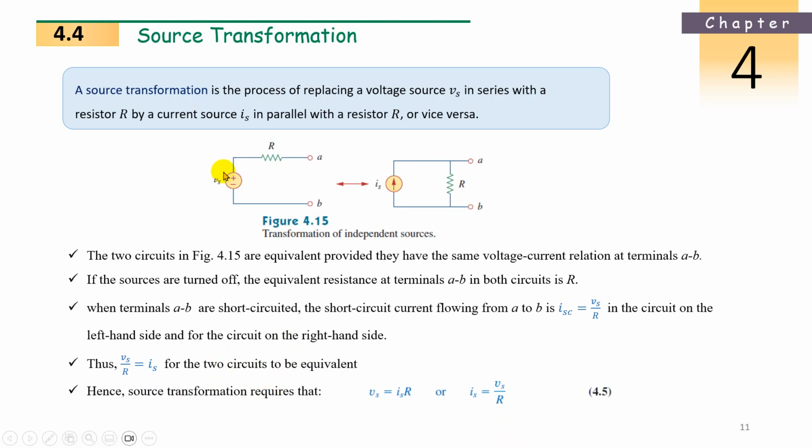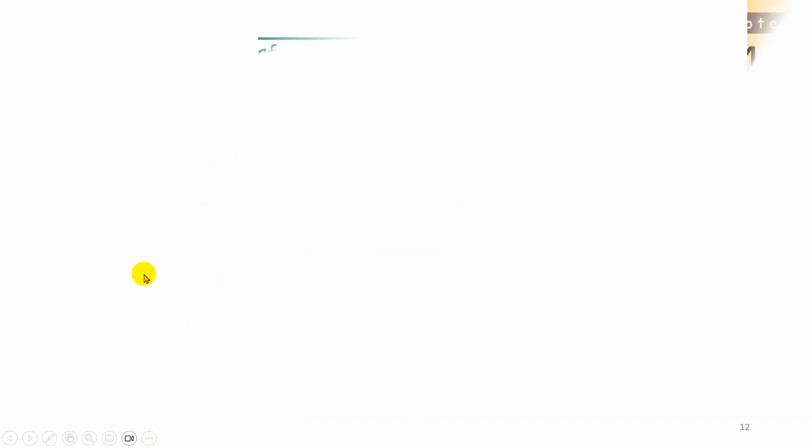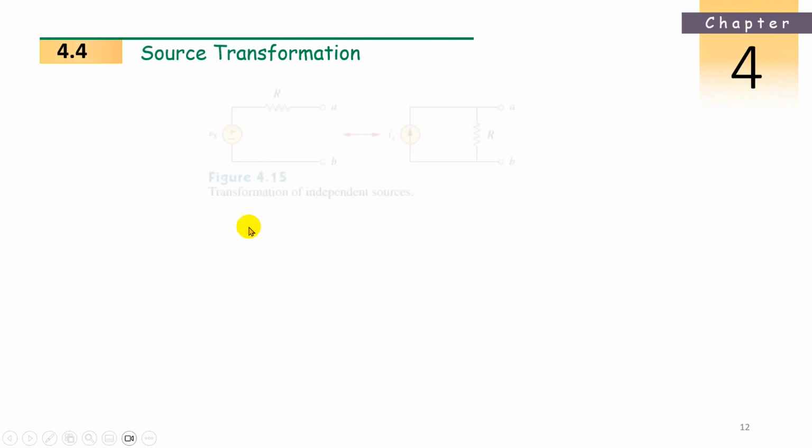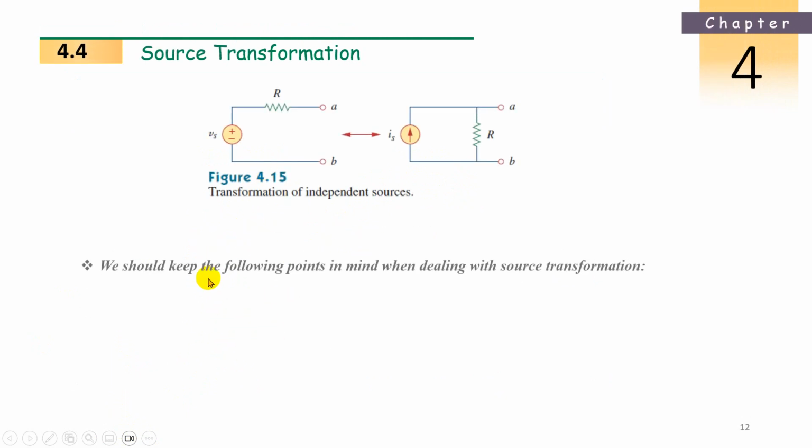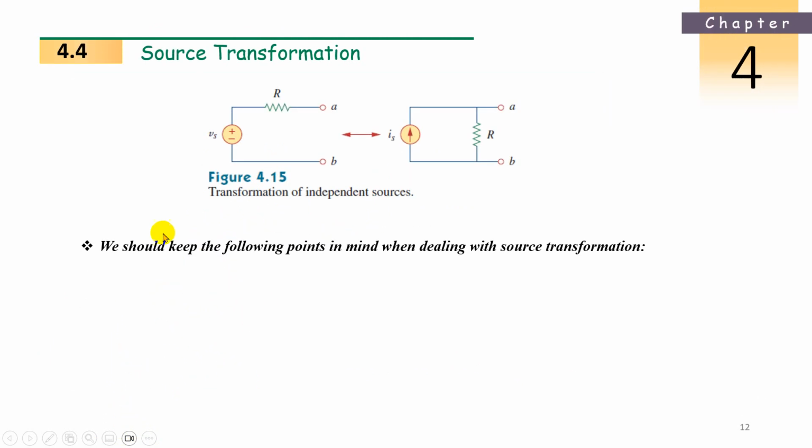Whenever you come across a voltage source with series resistances, if many are there, join them all together and make one resistance. The voltage source can then be rearranged as a current source in parallel with the resistor. With an example you can see, or with another basic law we'll see. Okay, what do we have to keep in mind?